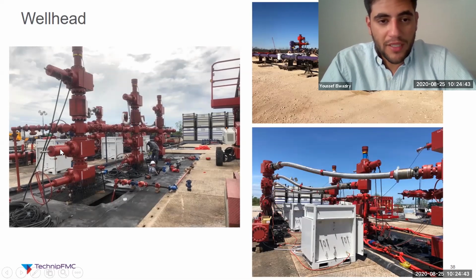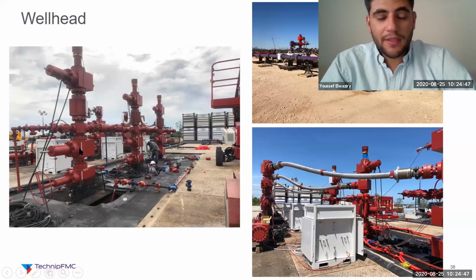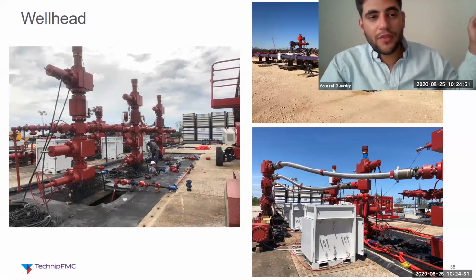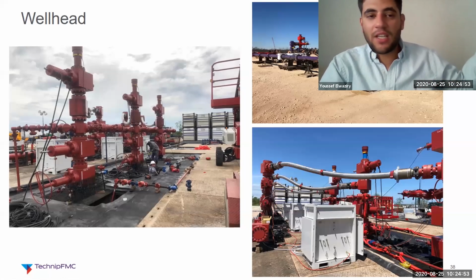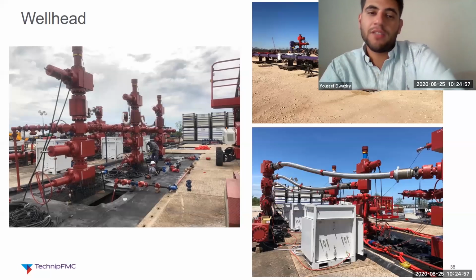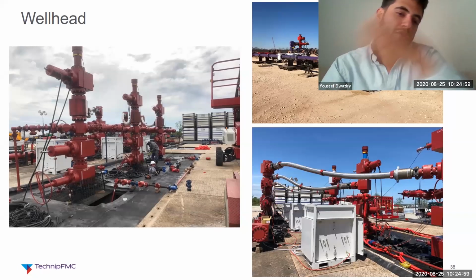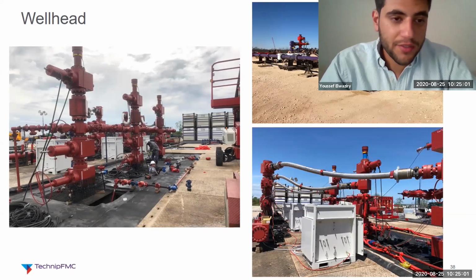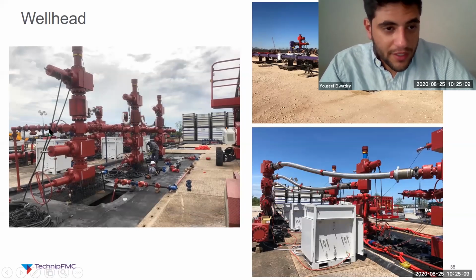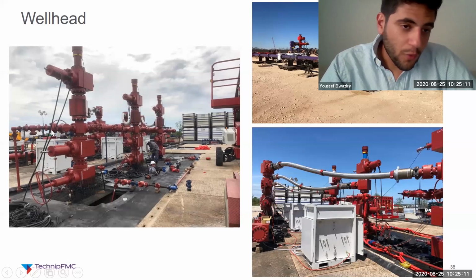There's another upper master valve that is hydraulic. And by hydraulic, it means that it's operated through hydraulic lines from outside of the red zone. So you might be outside like 100 feet away from the well, and you have a handle. You turn it to the right to close, or to the left to open it. And then this is another crown valve, which is usually for wireline. And then you have wing valves.